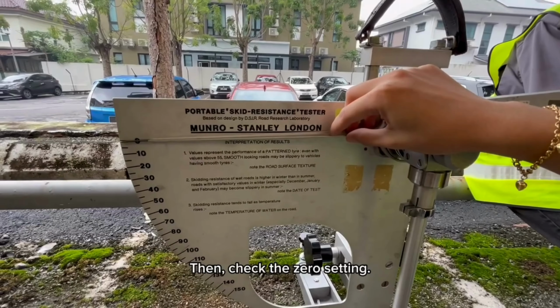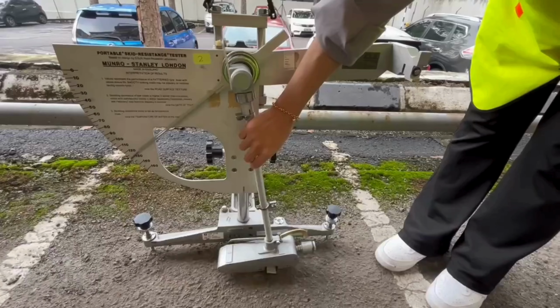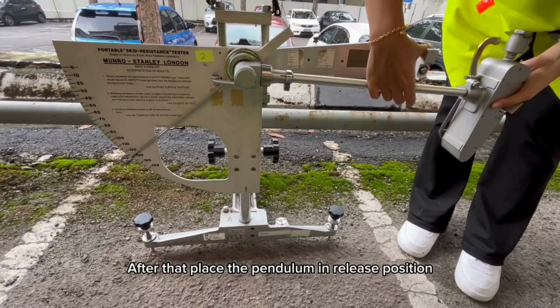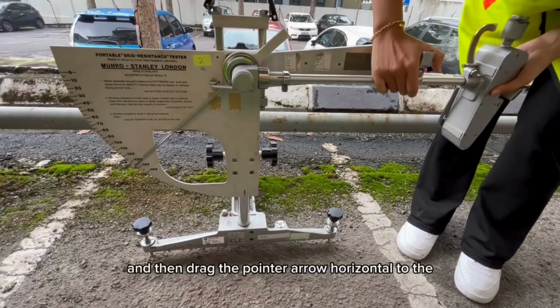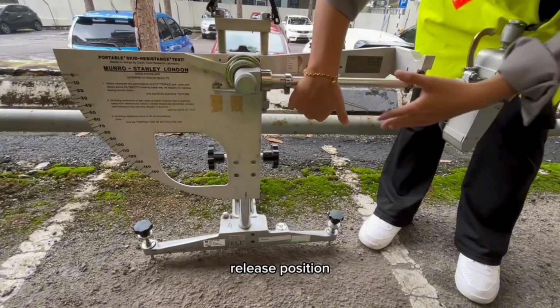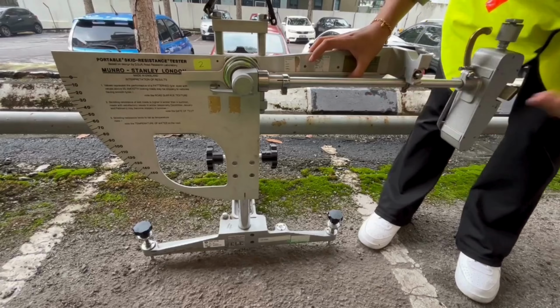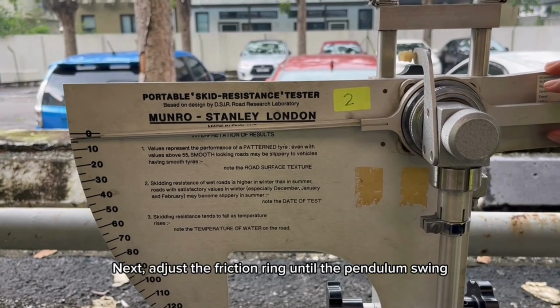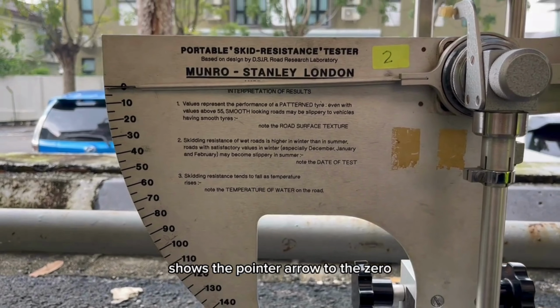Then check the zero setting. After that, place the pendulum in release position and then drag the pointer arrow horizontal to the release position. Next, adjust the friction ring until the pendulum swing shows the pointer arrow at zero.